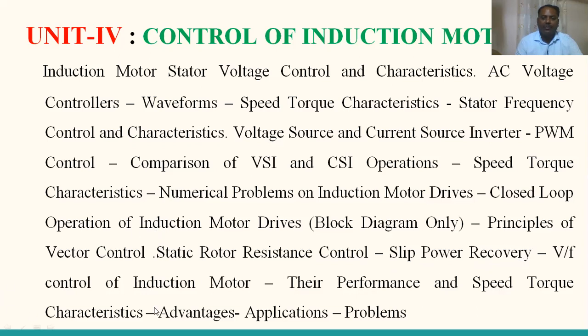All these we are going to discuss in unit number 4, the control of induction motor. Stator side methods are applicable for both types of motors, whereas rotor side is applicable only for the slip ring induction motor.